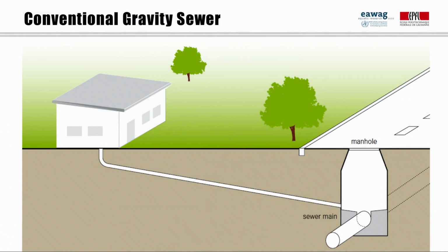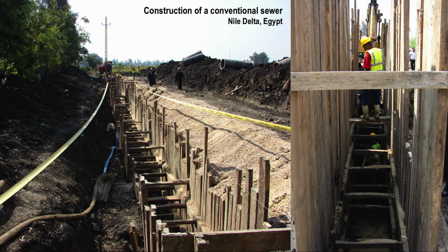Access manholes are placed at set intervals above the sewer, at pipe intersections, and at changes in pipeline direction. When the sewer also conveys stormwater, which is known as combined sewer, sewer overflows are required to avoid hydraulic surcharge of the treatment plant. However, nowadays, a separate drainage system for rainwater or local retention and infiltration are recommended instead, which leads to cheaper and more efficient systems.